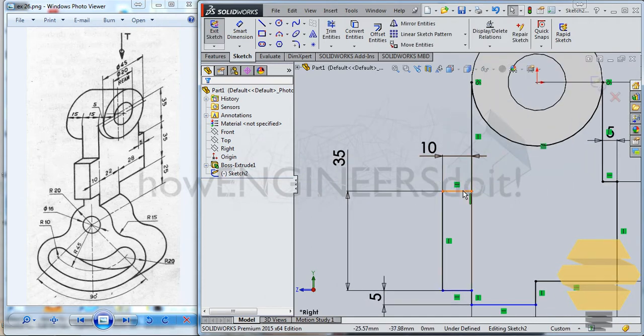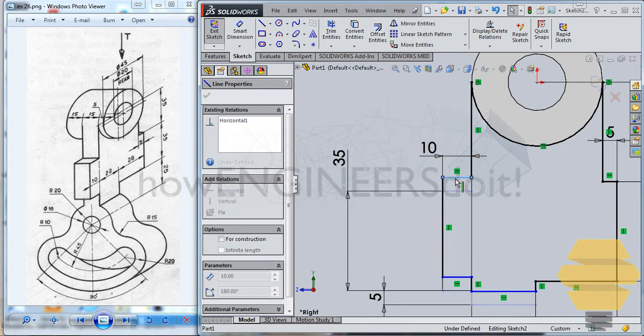So what I was trying to say is, if you're not able to get where exactly a dimension is missing, you can go to any other portion of the sketch where you have the blue color and just try moving it up and down or left or right. Left or right is not moving, it's moving up and down. So you need to constrain somewhere on the z-axis.